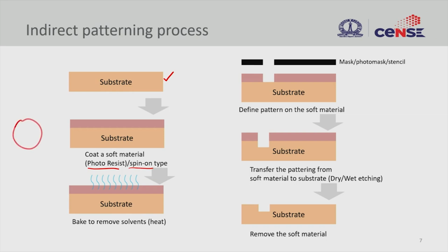This is one way of material transport. You put this material in a chuck, and then you rotate the wafer. If you drop cast this material, when you are spinning, it will spread. So I drop cast this, and when I spin this wafer, this viscous liquid is going to spin and uniformly coat the surface. We'll briefly look at how this spin coating works later on, but this is how you bring this material on top of the substrate.